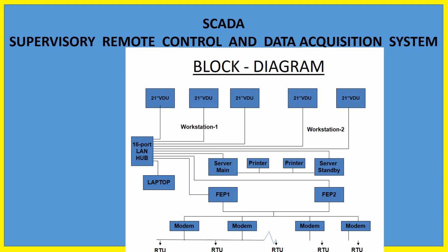I have not told you that the telecommand is demodulated in the field, in the RTU. Then the particular DC signal will come out and it will act accordingly. And in telesignal, they will modulate it in the RTU in the field, and then it will travel through the communicating cable to the control center. Again it will be demodulated.